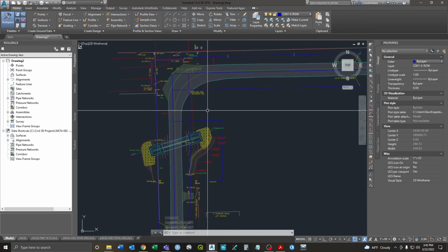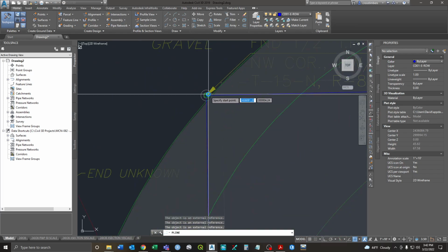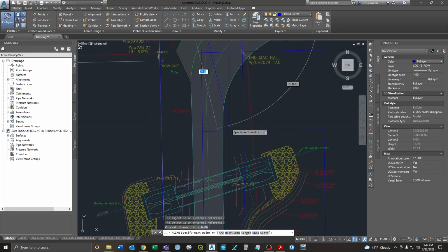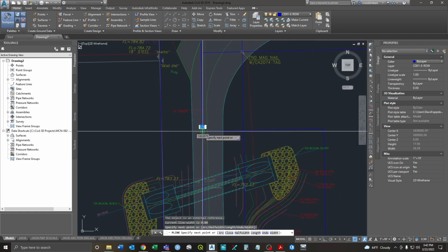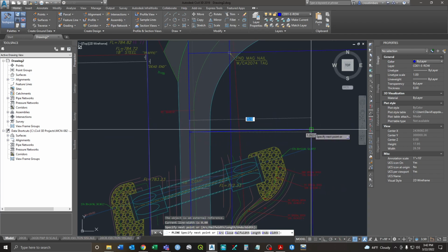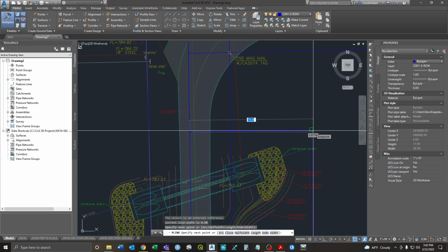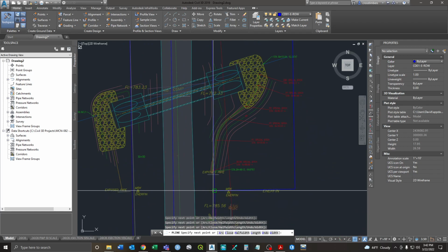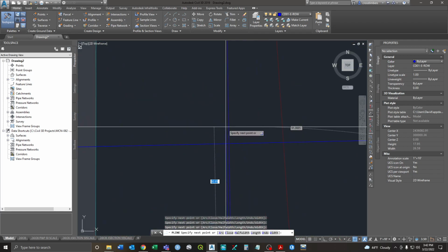And so now we're going to do our polyline, PL, from the start point, which is our section corner. Okay, and we want to come to here, and here we don't need to stop. We'll just go all the way across because it's the same bearing, and that's another reason it's easier if you use the same bearing. And then we'll just trace our thing, and then again we've got to do the intersection.